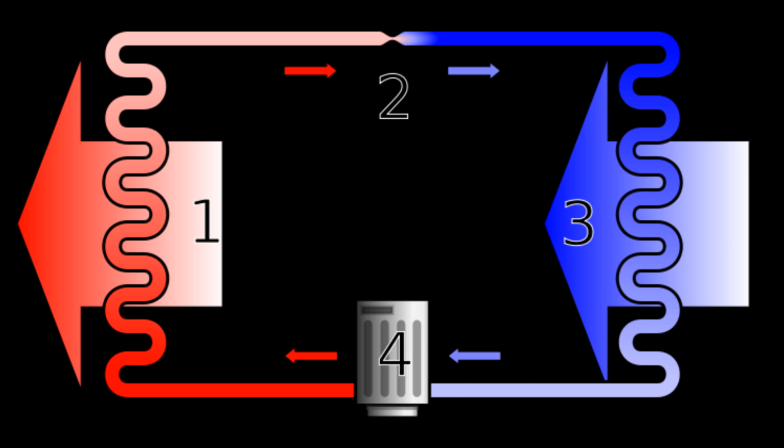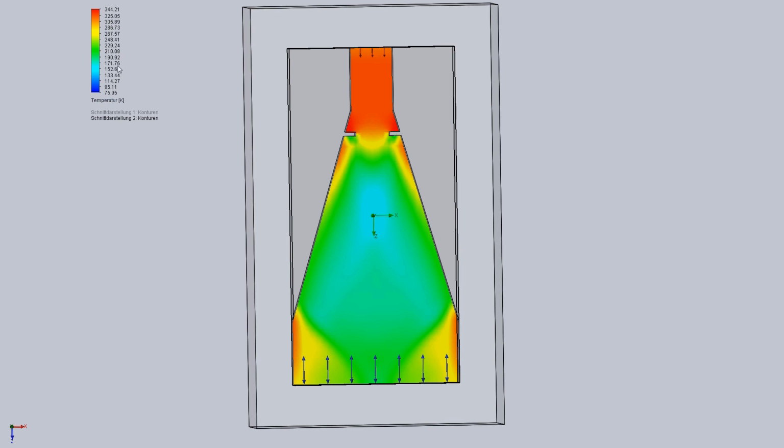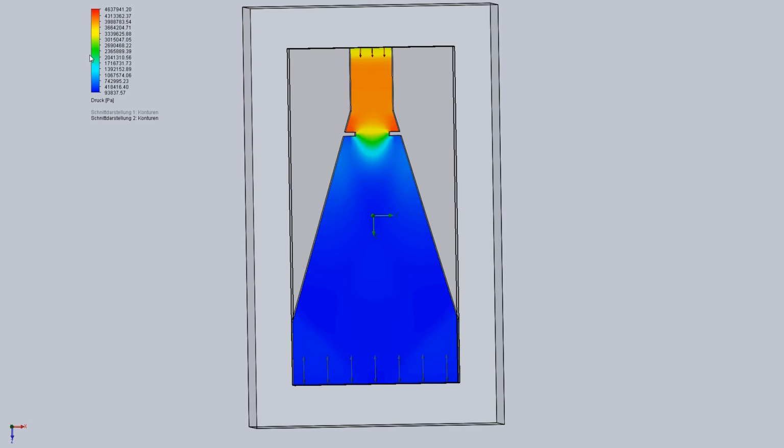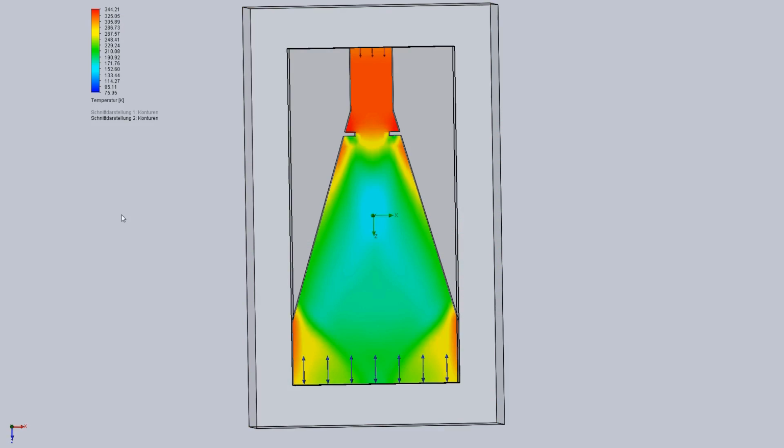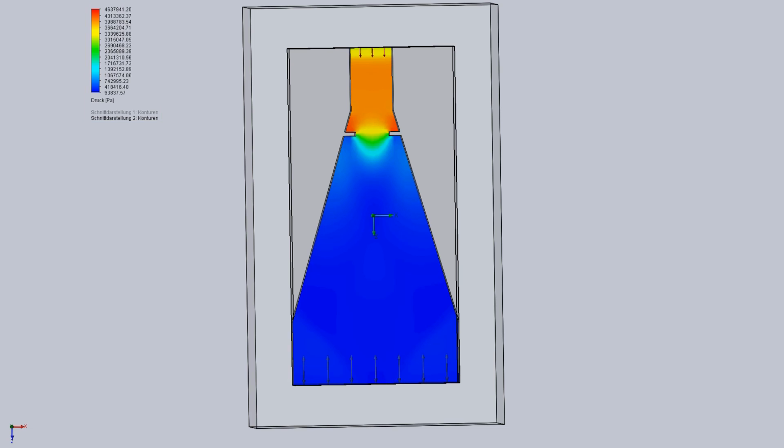Now the slightly less extreme but nowadays technically much less practical and much less used practice would be to just take a gas or liquid without changing its state and just pressurizing it and expanding it to change the temperature without adding or taking away heat, and then actually adding and taking away heat in the other two steps. You can expand the gas and thus cool it down below its original point and then take in heat, then pressurize it again, then give off heat as it is now hotter, then begin the cycle anew. But it's basically the same process and much less effective and slightly simpler to do, and it doesn't find any use nowadays.